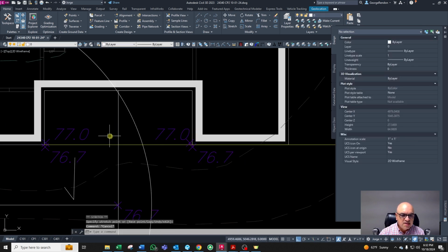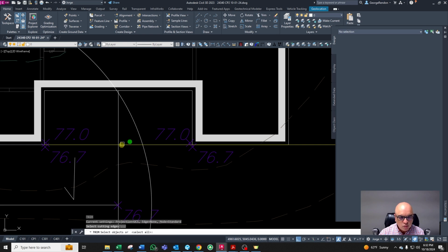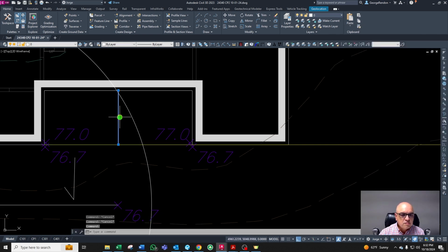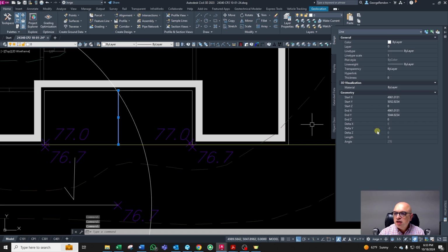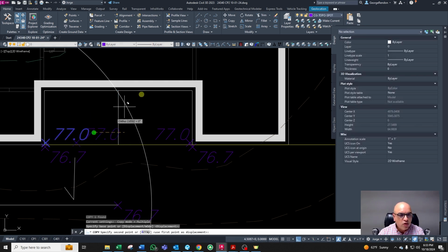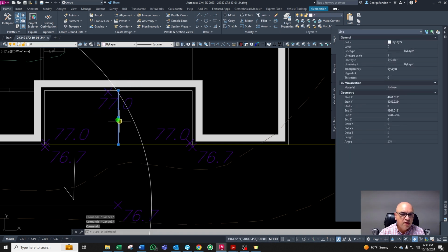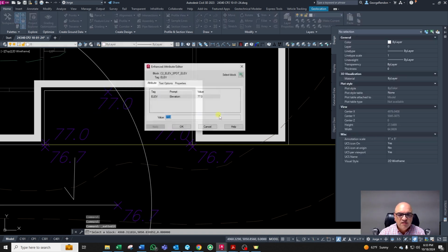Now, what is my distance between the house and the porch? Is that distance right here. What is the distance? It's going to be 8 feet. So again, 8 feet, then we need to come at maximum 2%. 8 times 0.02 to be at 2% is 0.16. Let's make it 0.1. So the house is 0.1 at the door. So this is going to be 77.1.